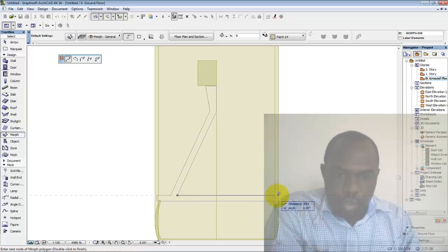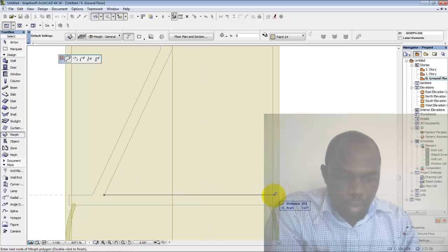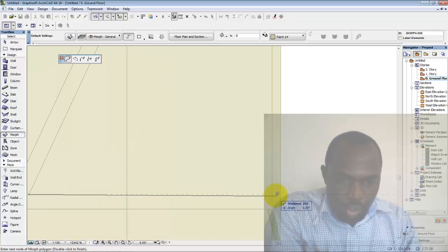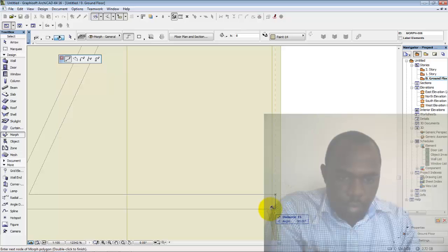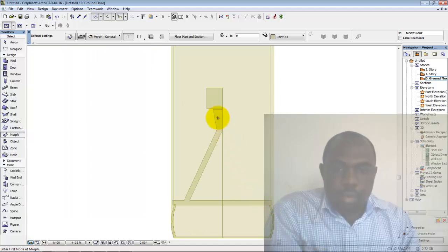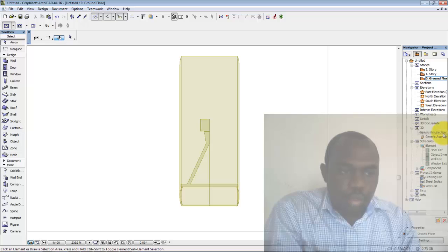So that does it for that one. So you go to horizontal now. We want it midway between these two lines here, so we specify about 255, enter. Then go down, then click. So that completes the section for the tire's wheel.